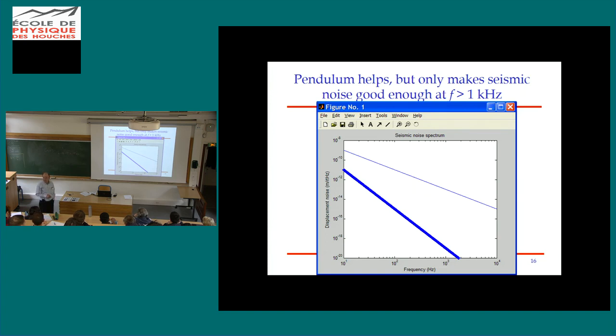So this was really easy to do, okay? Just pull that line down by how far below unit transmission that frequency response function was at each of those frequencies. So anyone could do this in their head or with a little graph paper. All right, now here's my target level. I reach it at about 2 kilohertz or about 1 kilohertz here, but not 100 hertz. I'm still far away. But I'm invited to think about linear processes like this in terms of, well, let's cascade several such systems, one from another.